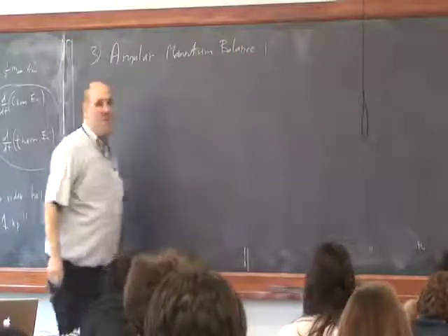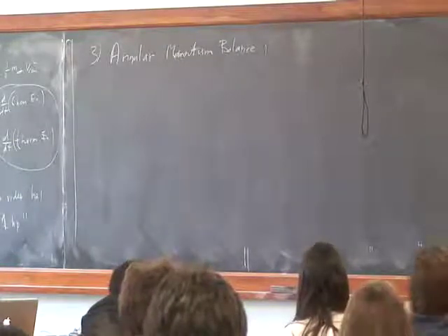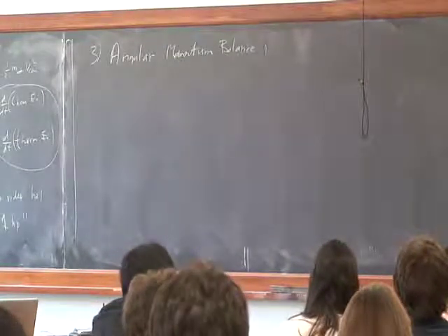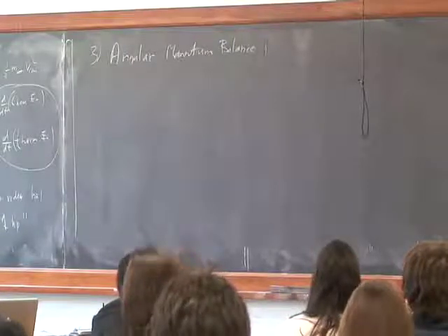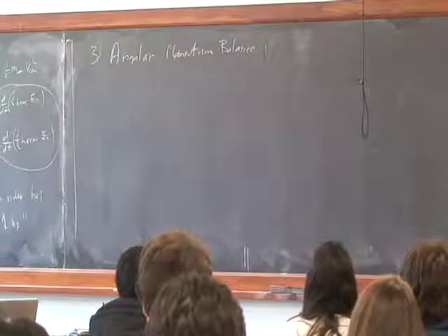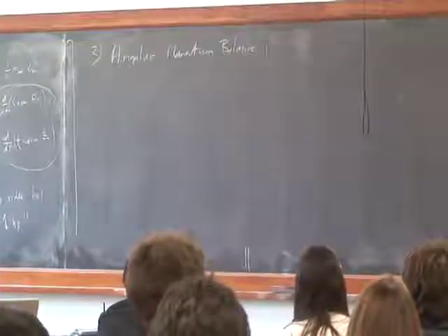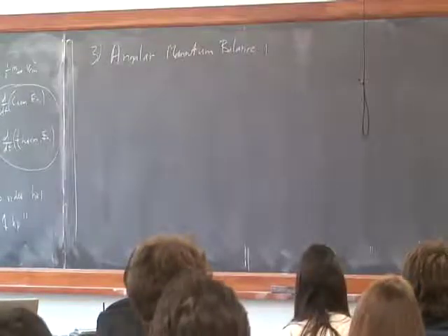And we have this cartoon equation for angular momentum balance, which is torque equals I alpha, just like for linear momentum balance, we had this cartoon equation, F equals ma. It turns out for linear momentum balance, that is the whole right equation, like I just showed you. Total force equals total mass times acceleration of the center of mass. For angular momentum balance, the cartoon equation is wrong.